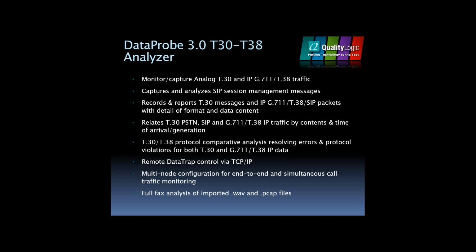Since we are looking at basically a two-ended transmission system, what we try to do is provide the capability to look at the analog signal with the data traps, and then we actually directly tap into the IP connection using a network interface card in the DataProbe host computer. So that gives us a capability to look at the entire process.